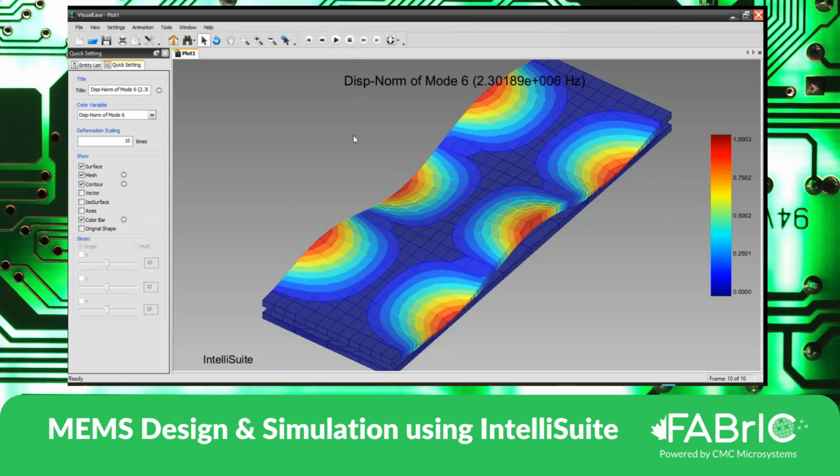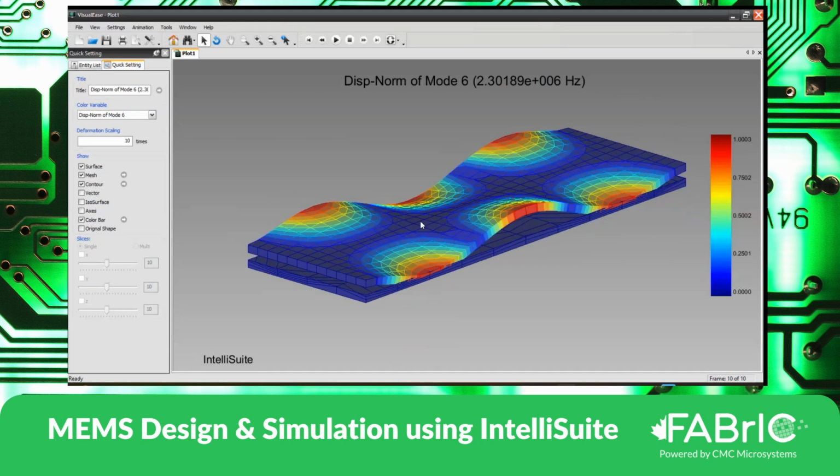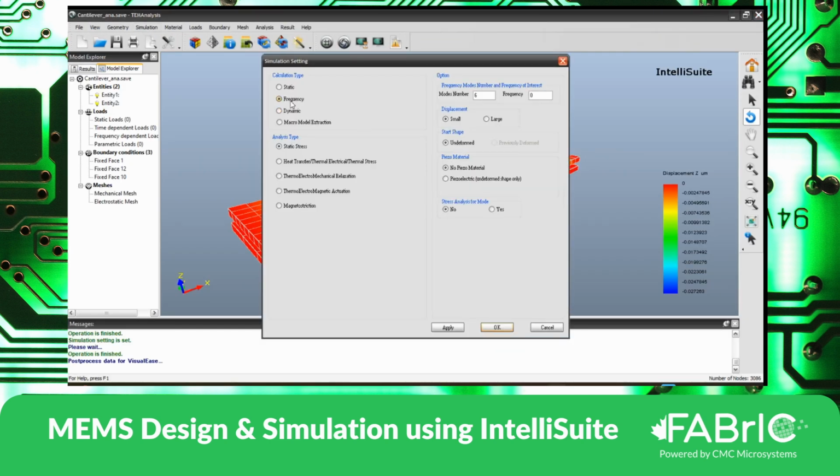Okay, so this is how we can identify the natural frequency of the device in various modes of vibration. Save this. Now, when I select frequency, I have the option of the analysis type. It's not just static stress. Static stress is selected to identify natural frequency through the simulation.